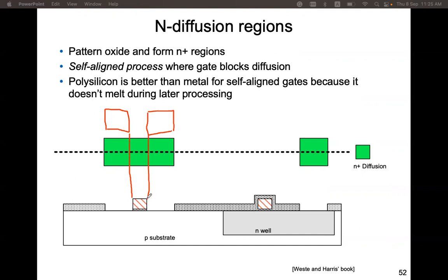Through forming the polysilicon layer first, people can solve a lot of problems very cleverly. So instead of two separate N regions, we use this single N plus mask that covers this gate region.